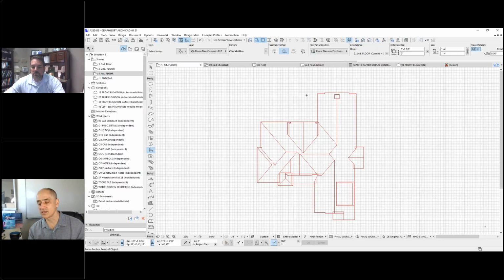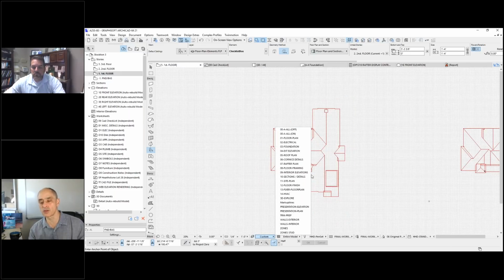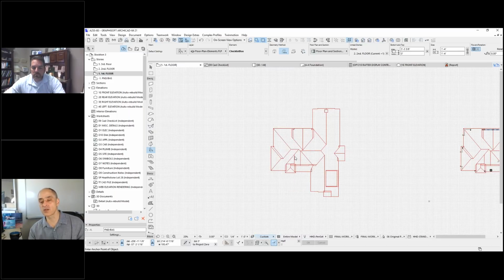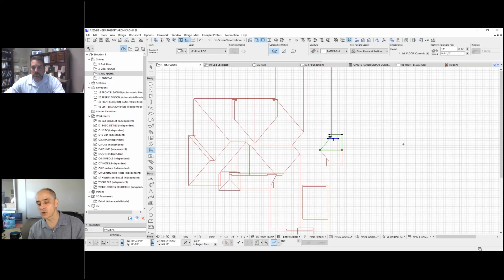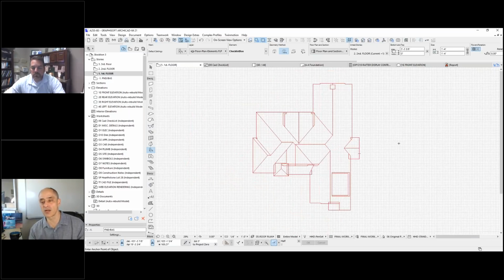set of options. So when you do that, it creates a whole bunch of objects that match the current geometry of the roof. In other words, it looks at the roof slopes and the roof outline, and it puts in things based on rules. Once you do that, you can actually move or change the individual elements because they are objects, and you can list them. So it's a quick way to get the basic framing set up.